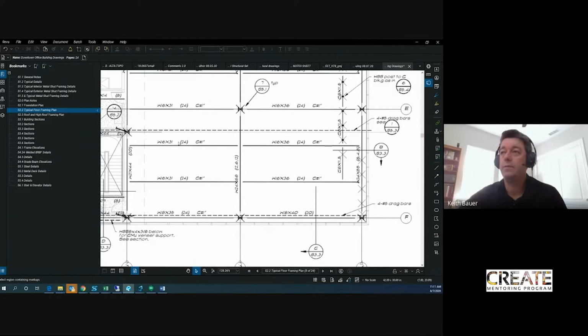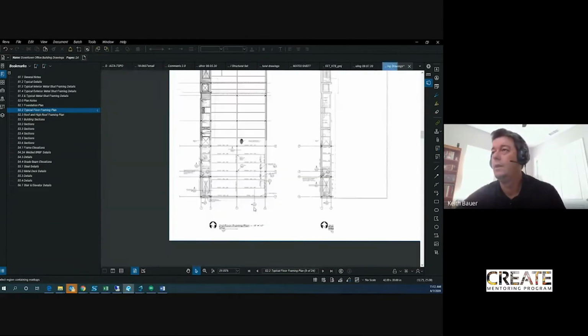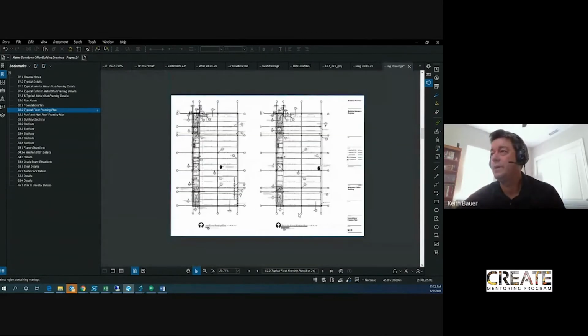And then this will be in the plan notes as well. This 24 means that's the number of studs on top of the beam. There are little pieces of steel that get welded to the top of the beam and embedded in the concrete floor slab to tie them all together. And then C equals 1 inch. Again, this will be defined on those plan notes back on S2.0. And I'm not going to tell you what that is. You have to look that up, because that might be one of your questions. In any case, you'll see a lot of information like this.